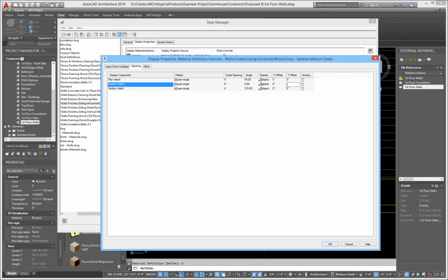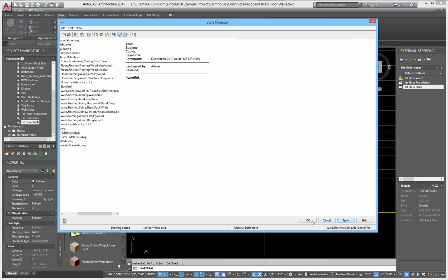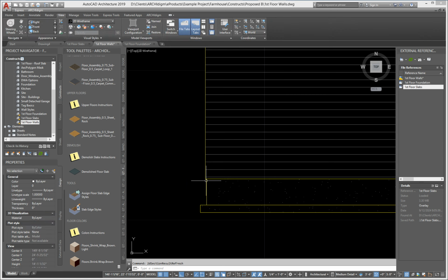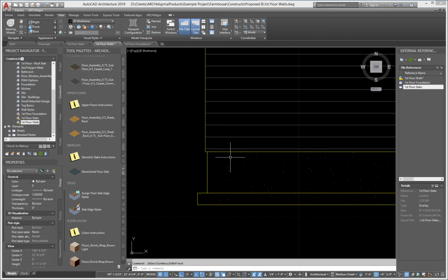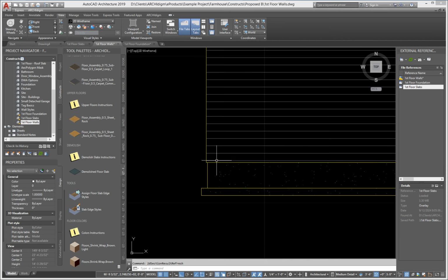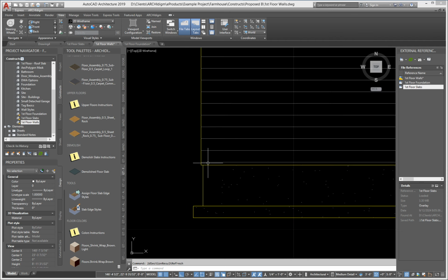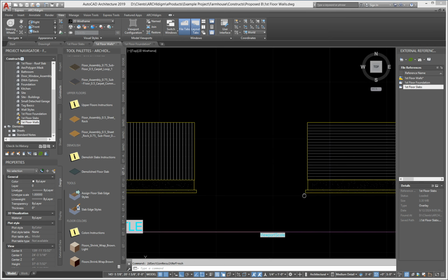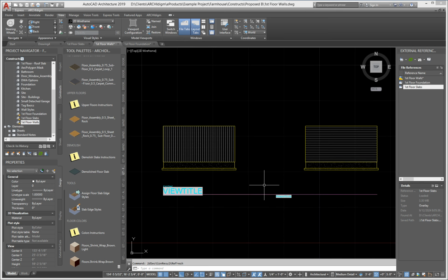Maybe 0.125. And the issue, again, is that you get the gap at the seam. That's really where the problem occurs. So that got better, but I don't like this line down here. Maybe I'll keep tinkering with that and pushing it down until you wouldn't see it in your prints. If it doesn't bother you, great. For some, that's unacceptable. For others, it's okay. I think that pretty much covers how to work with the merge material checkbox to improve your line work.